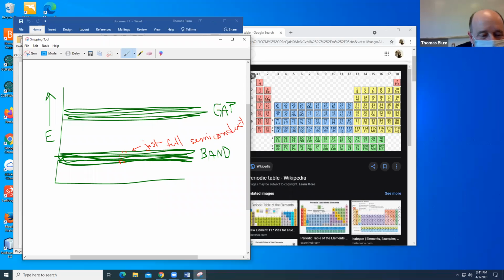Okay. So now the idea is doping, and silicon or germanium are semiconductors. But if you dope it, let's say I dope silicon with aluminum, then I have mostly silicon but a little bit of aluminum. Aluminum's relatively similar to silicon. It's near it in the periodic table, but it's in a different column, so it has fewer electrons on the outside. So the bands are mostly the same as what they were before, except now when you dope with aluminum,